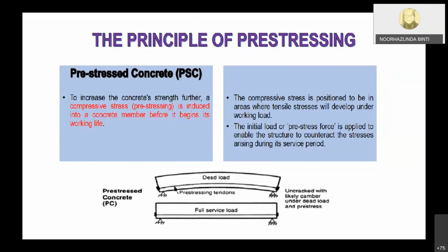But instead of just embedding the steel, this time we pull that steel into tension, and then we induce compressive stress in this concrete. So the initial load, or prestress force, is applied to enable the structure to counteract the stresses arising during its service period.